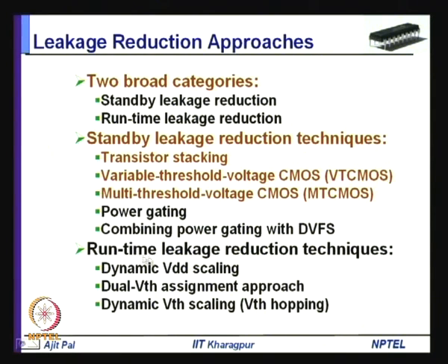And then there are runtime leakage reduction techniques, and I shall discuss 3 of them: dynamic VDD scaling, dual VT assignment approach, and dynamic VTH scaling, which is also known as VTH hopping in a particular situation when you have only 2 threshold voltages. We shall discuss these techniques one after the other, and today we shall focus on these three approaches: transistor stacking, variable threshold voltage CMOS, and multi threshold voltage CMOS, MT CMOS. So, these 3 techniques we shall discuss today.